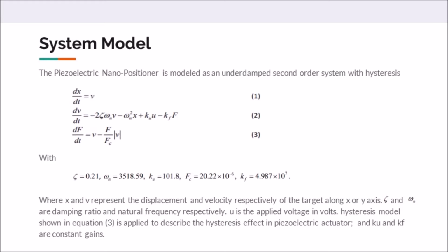The zeta you see at the bottom of the slide has a very important role to play in the entire system. It is a damping ratio and characterizes the frequency response of a second-order ordinary differential equation. The damping ratio is a dimensionless ratio of two coefficients of identical units. It is a system parameter that can vary from undamped, where zeta equals 0, to underdamped, where zeta is less than 1, through critically damped, where zeta equals 1, to overdamped, where zeta is greater than 1.